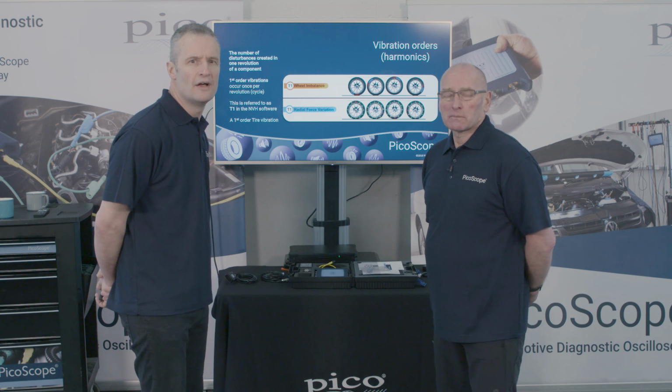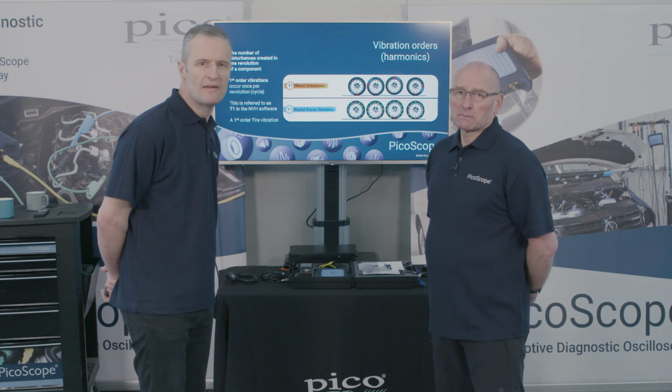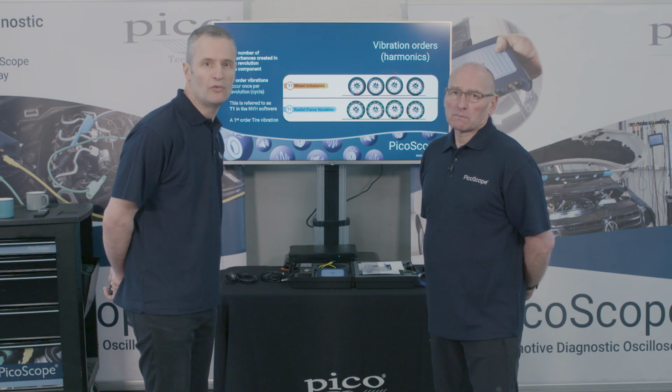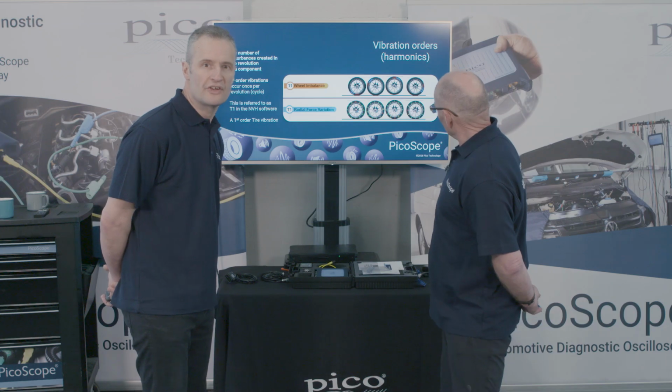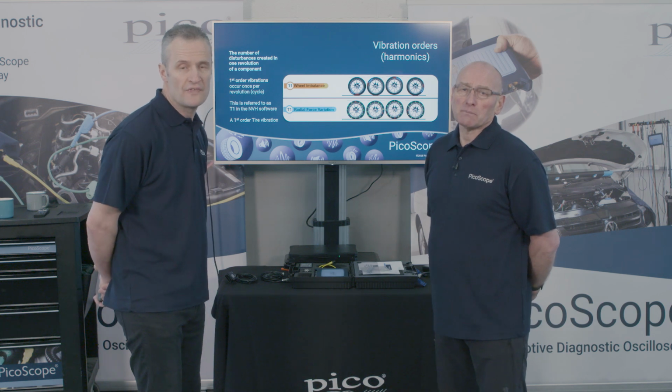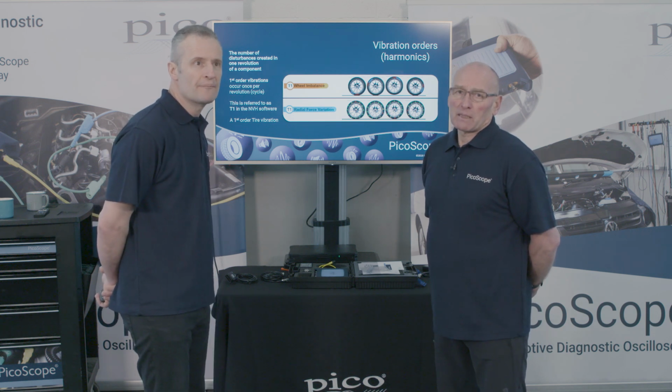So vibration orders, this is something that we need to grasp. To understand what a vibration order is, it's no more than the number of disturbances per revolution of a component. If you think about an oval wheel, for example, 1 revolution, 2 disturbances. So here we have an imbalance. That's a classic example: 1 disturbance per revolution of the wheel, or radial force variation, and this is where